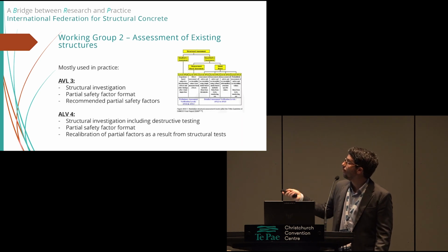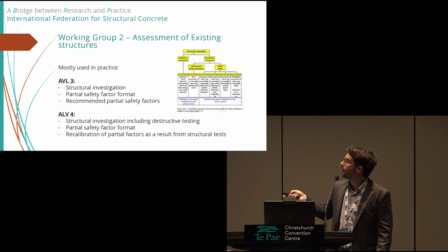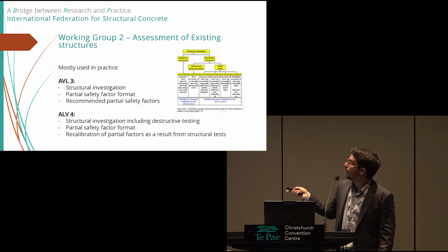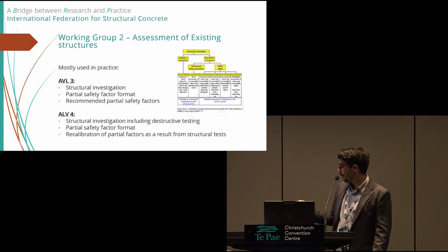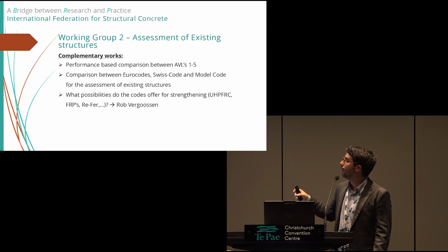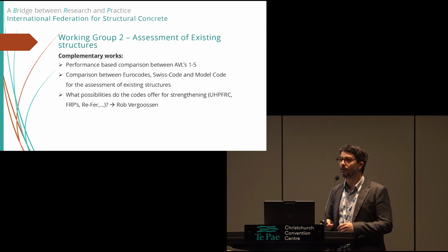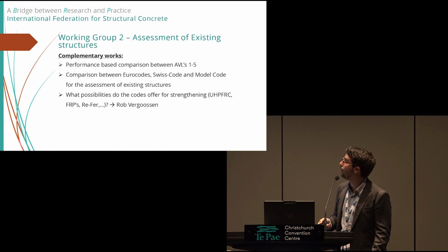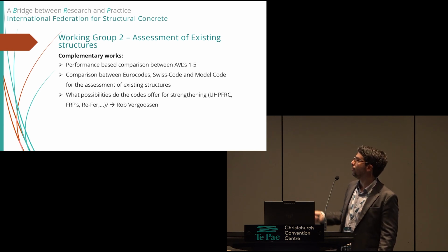Mostly what they use in practice is level 3 and 4, for structural investigation, partial safety factors, and the recommended partial safety factors. So they go through those, and these are the most used in practice, but they are going to compare each level with a performance-based comparison, and also check if it's complying with the Eurocode, the Swiss code, and also the model code.